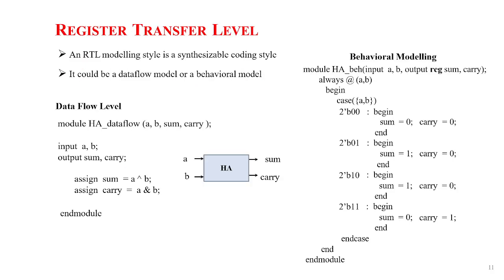Next is RTL, register transfer level. In the RTL we need to use which modeling? That is data flow modeling and behavioral modeling. RTL modeling is a synthesizable code style. Synthesizable code style means what? We can convert it into hardware.